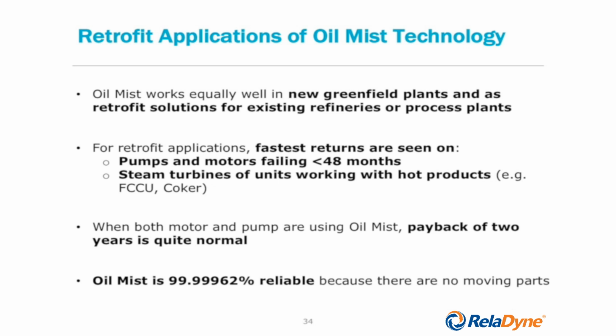The answer to that question is that the unreliability is usually something that has been caused by human beings. If you allow the oil mist generator to run without having any oil supply, without having refilled the refill vessel for that oil mist generator, well then of course there is no longer any mist being generated.